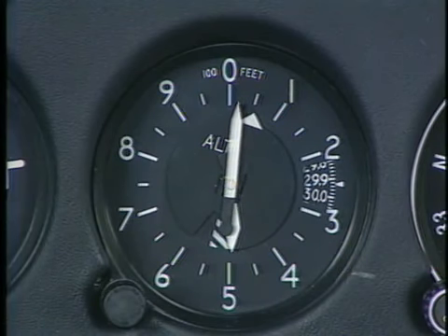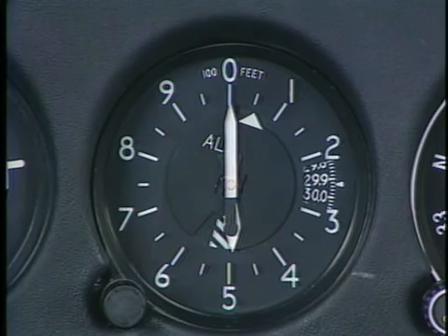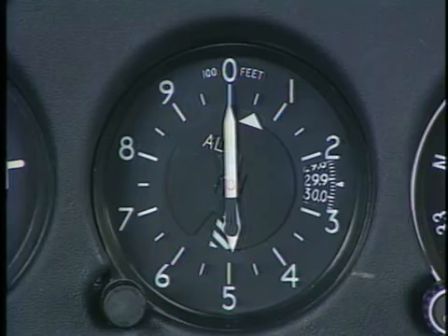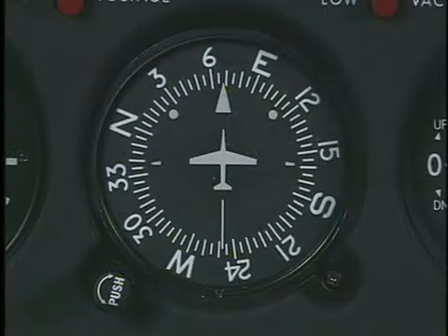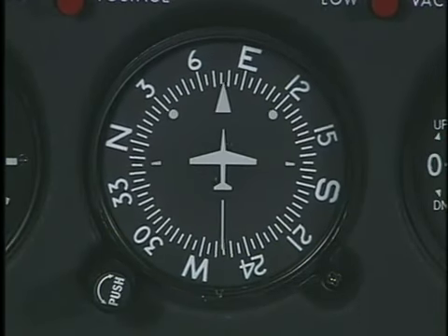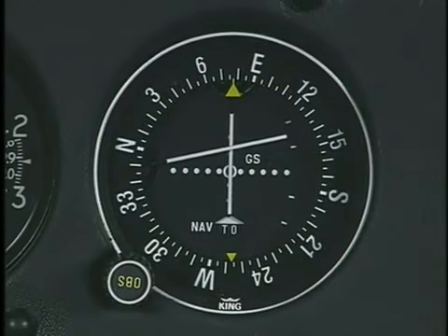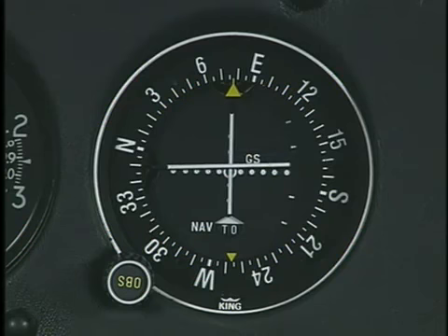Maintaining the altitude assigned by the controller is very important. Controllers assign altitudes that are at or above the minimum vectoring altitude, which provides both obstacle and terrain clearance. Do not descend from this altitude until you are established on the final approach course. Your clearance for the approach means you are expected to intercept the final approach course and fly the approach as charted without a further clearance. However, at a tower-controlled airport, this is not a clearance to land from the approach.